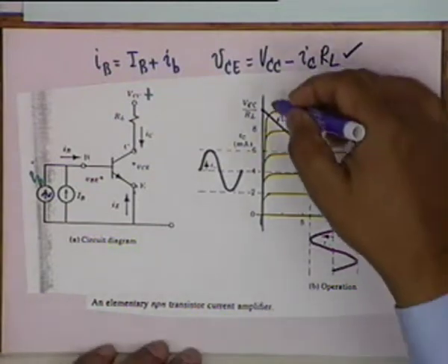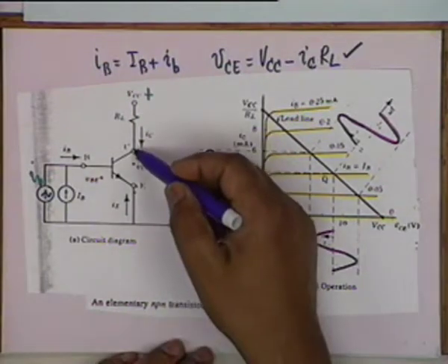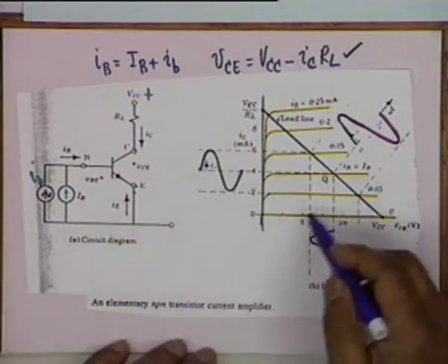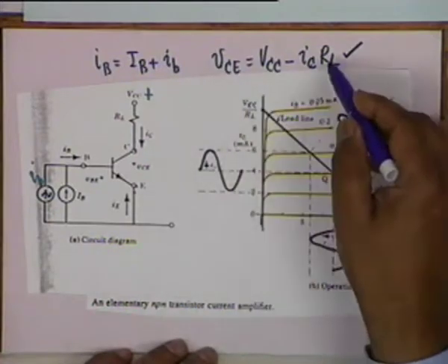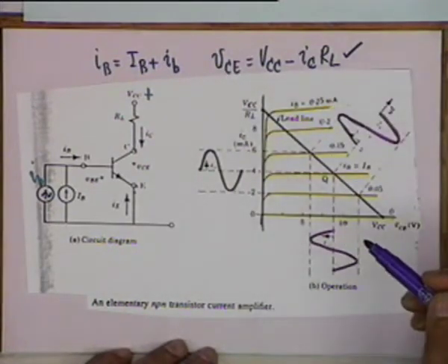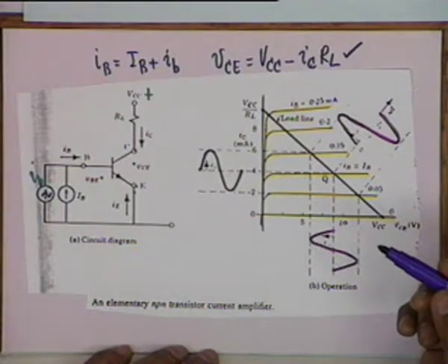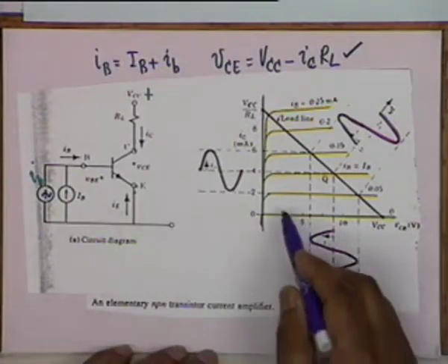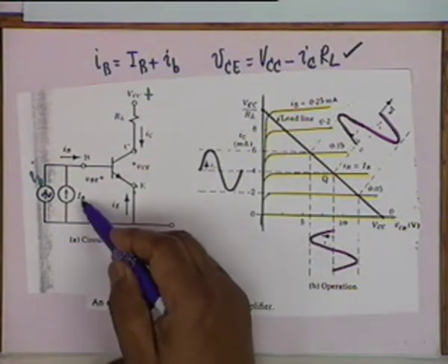Now, to find out where the transistor operates, that is, what would be the value of VCE and I sub C, it must satisfy two equations. One is a nonlinear equation specified by the characteristic curves. The other is a linear equation specified by this line, and therefore the intersection of these two shall determine the operating point of the transistor, or the so-called Q point of the transistor. And if I figure out from the characteristic curves which one is the curve for the specified value of IB,